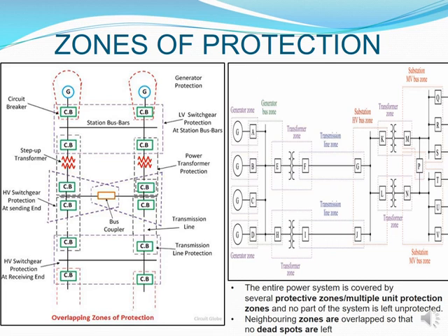And what does it really mean? If you had a fault in that bus bar, then we would expect all four of these circuit breakers to act or to trip on that fault. And if all four of them trip on that fault, what does it mean for your generators? By default, for this type of system, it means that your generators will also be out of supply and the supply onto the entire system will be lost.